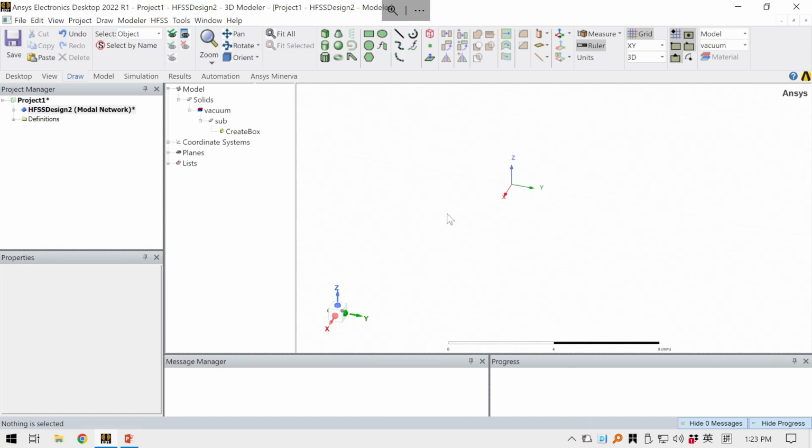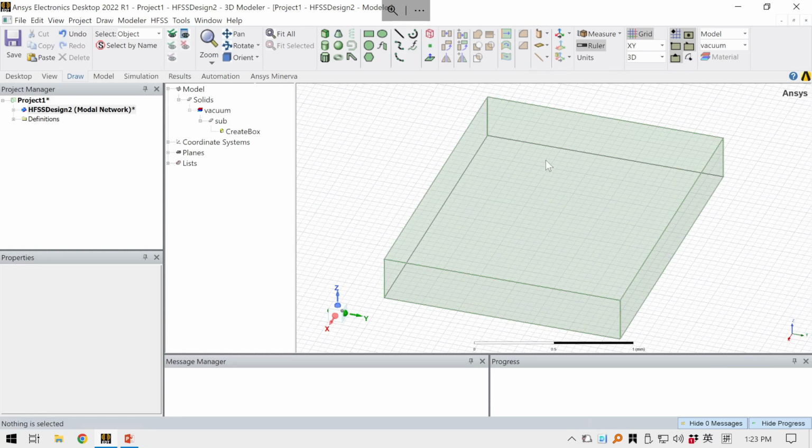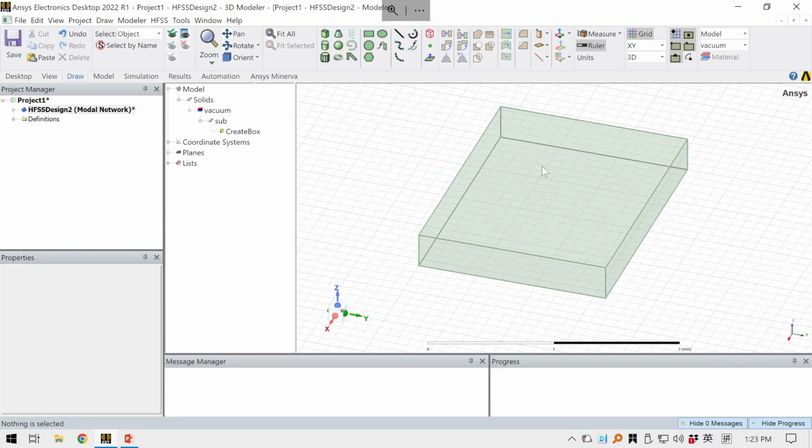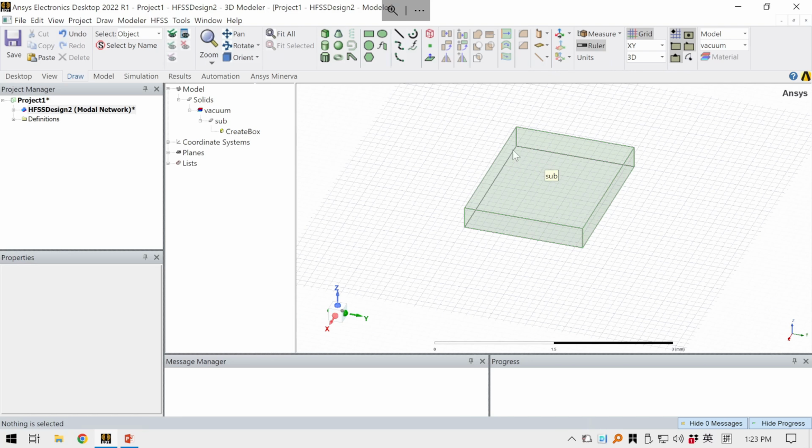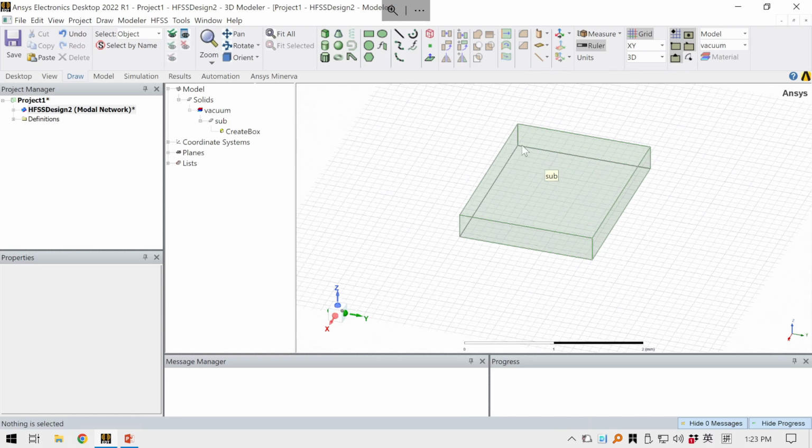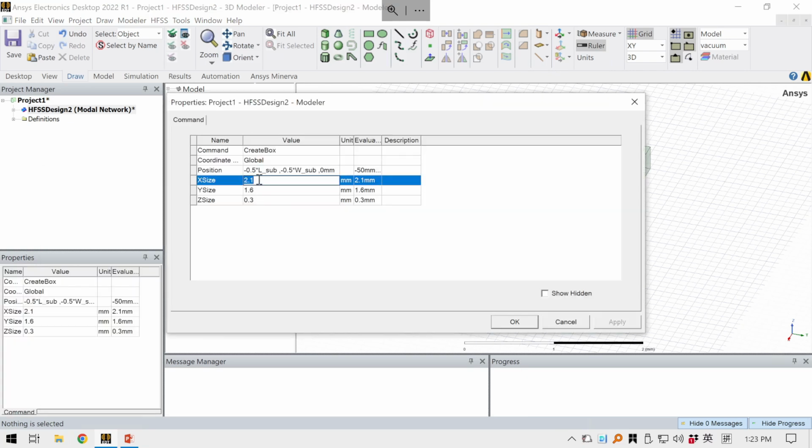Here we cannot see anything because previously our drawing is so small. So you can press Ctrl D and you will see it. This is at the coordinate of -50, -50 and 0, and the size is quite small. You can see this ruler here. The scale is like 2 millimeter on my side, because we didn't change the x size and y size here. So let's do further.